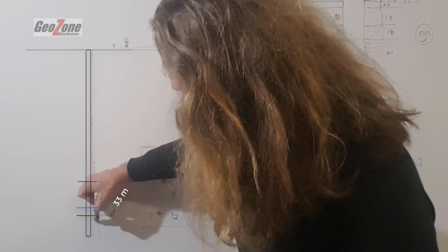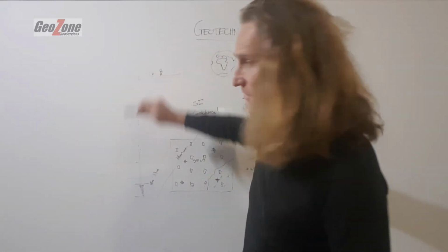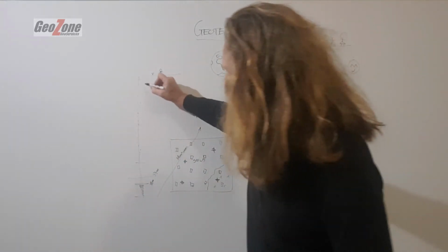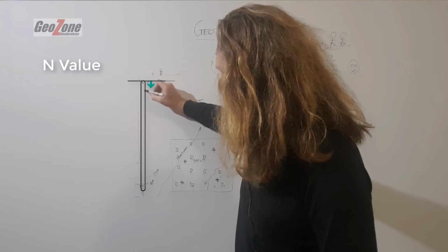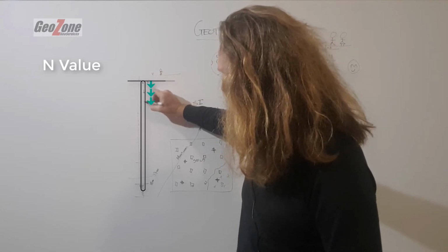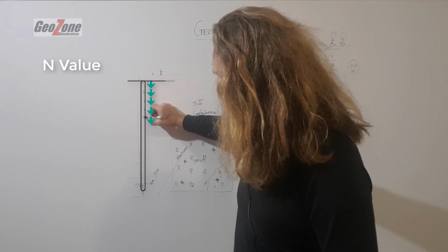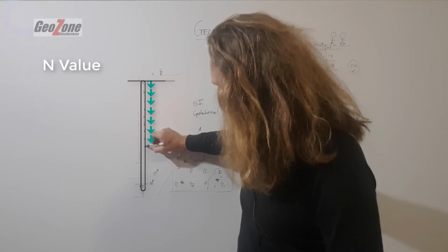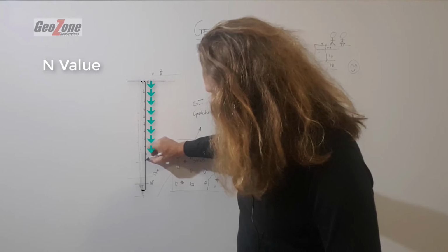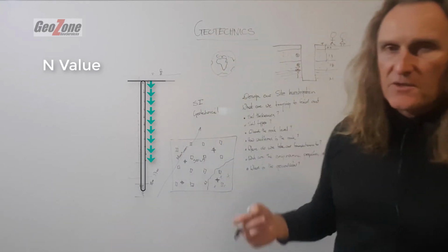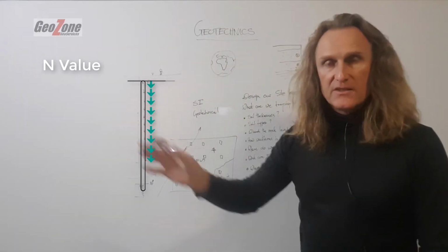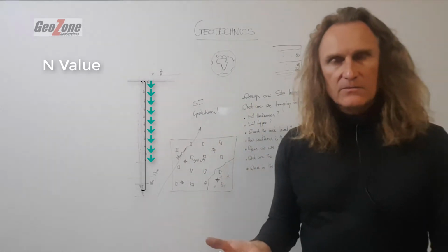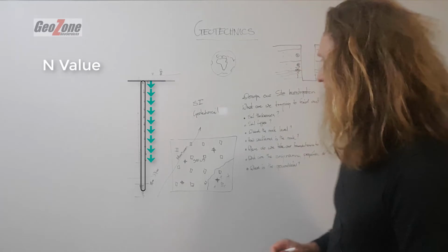Fantastic. So we get drill cores here. We log that. We log the soil profile. We start to understand what's going on. We put several of those boreholes there. We do standard penetration tests. We get the N values every 1.5 meters. There are issues around that test too, but this isn't the place to talk about that. So we get a profile of the soil in terms of its N value, which we can put into the bearing capacity equation. And hey, we're building our geological model.